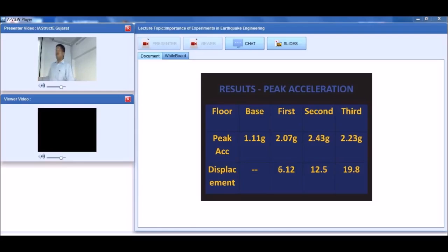What is the displacement? The advantage is displacement. When you make a structure stiff, you definitely get the advantage. Displacement will reduce. What is the displacement? Earlier it was 53 something. Now it will become only 20. So when you make your structure stiff, it is going to attract higher earthquake force, but at the same time deformation is reduced. That is the advantage. Right? Next.